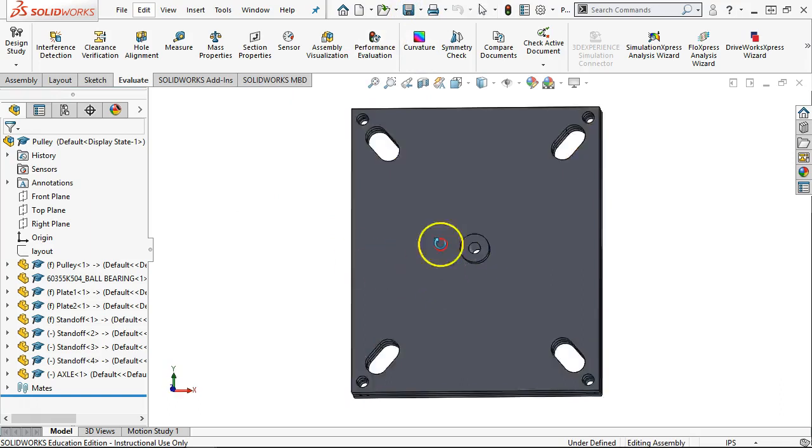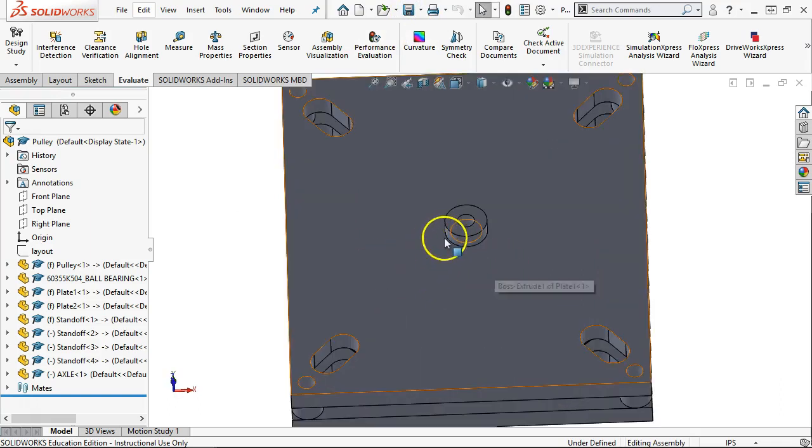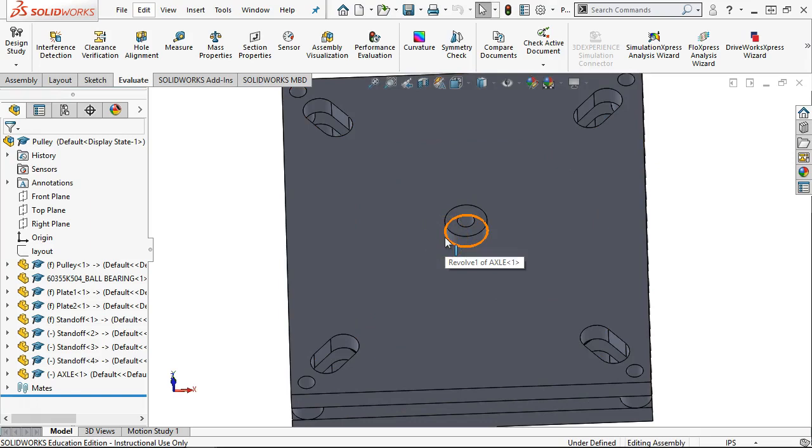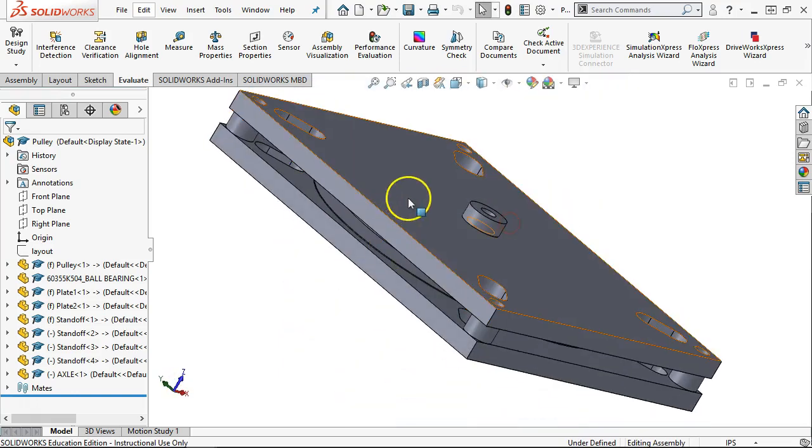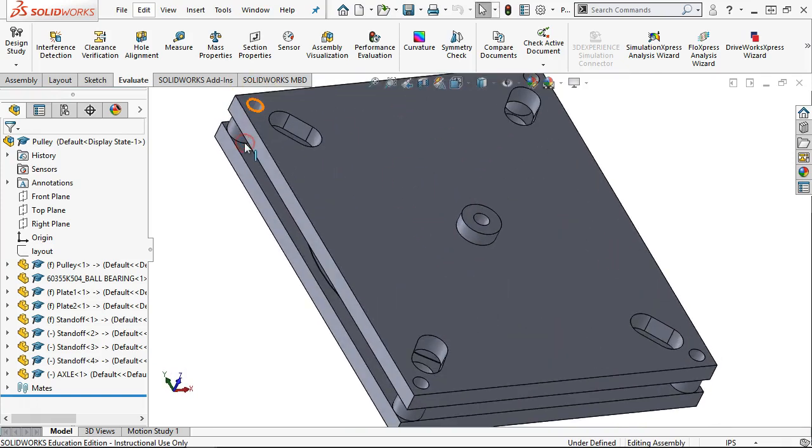As I went through this, I was thinking the holes in this plate really aren't that critical, but they do become a datum. So that 375 number, this pin should easily slide through and then go through the bearing, which is clearance for the bearing. Then it comes down to these holes, and typically you're just going to make them enough oversized, like the 201, or I take my guess and say, oh, I'll just make it 190 and I'll adjust it later.